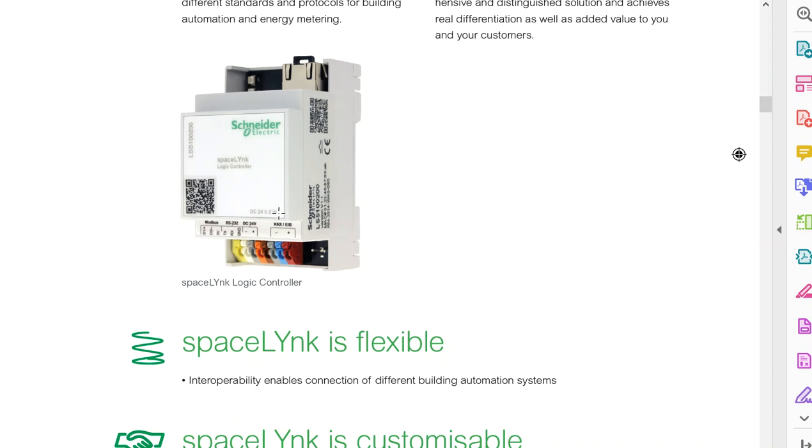It has the KNX port here, and it also has the KNX IP interface inside of it, so it makes life easier. It is directly connected to the KNX and directly connected to the IP. It has some software inside. You can configure it according to your group addresses and make the visualization happen.